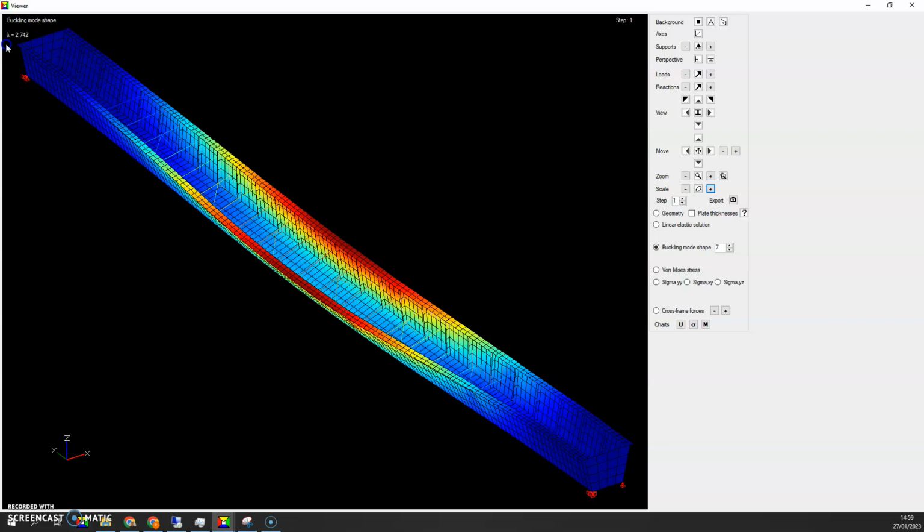So this is a really inexpensive way to substantially increase the torsional stiffness of your tub and prevent global lateral buckling modes such as the ones that unfortunately and tragically led to the death of 3 workers back in 2001 in the state of New York.